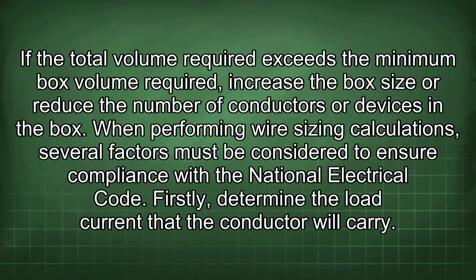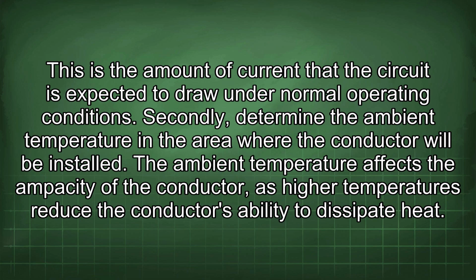When performing wire sizing calculations, several factors must be considered to ensure compliance with the National Electrical Code. Firstly, determine the load current that the conductor will carry. This is the amount of current that the circuit is expected to draw under normal operating conditions.